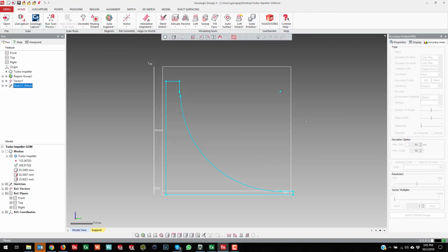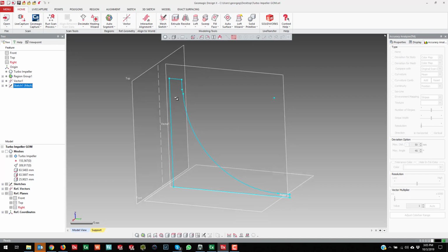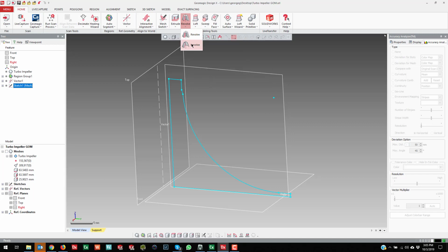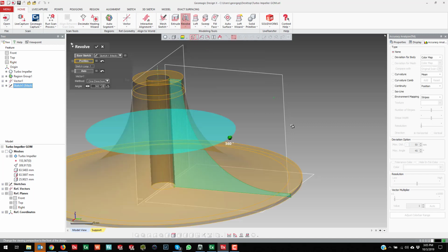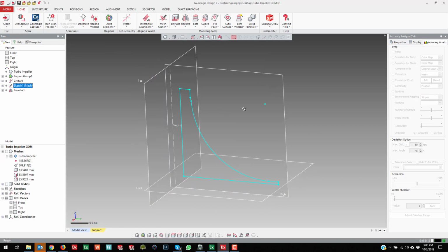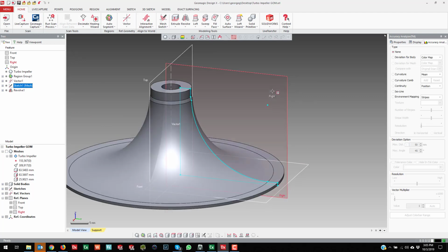And you can use the right click menu there to exit out of the commands and exit out of the sketch as well. Now it's time to do a revolve. There are two different kinds of revolves in here: a revolve solid and revolve surface. We're going to do a revolve solid in this instance. I point that out because later on we're going to do some revolve surfaces. So you see that it disappeared when I hit OK. That's because the solids are hidden.